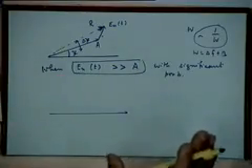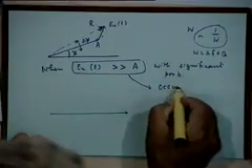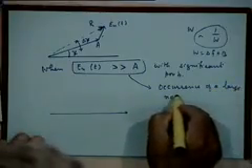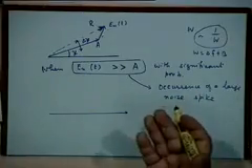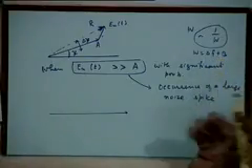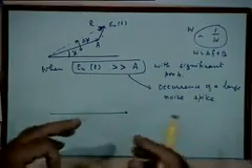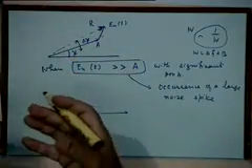So a few statements that I made here are very significant. First, this event has a significant probability, and this event essentially means occurrence of a large noise spike. And the duration of this spike, whenever it occurs, is going to be of the order of 1 by W. These are the 2 or 3 statements I made. Right? So what happens during this duration? What happens to this phasor diagram when such a large noise spike occurs? That's what we need to understand.